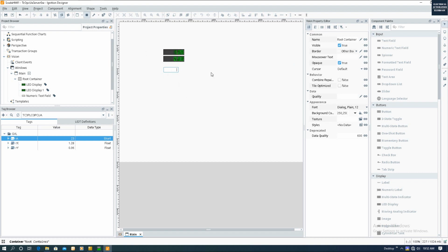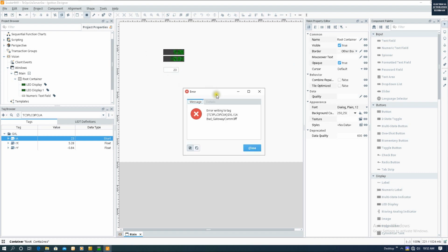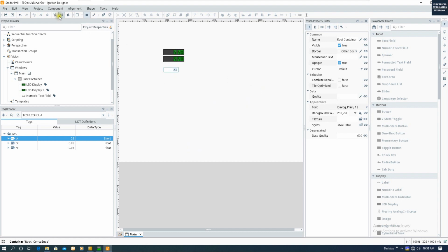So now I can type in a 45 value. Then we will find the system will pop up this message. It doesn't allow us to write the value in here. That's because there is a protection mode here. By default, that is the read-only mode. This is actually a very good feature. In case, for some reason, you accidentally type in a value, that value can directly write into the PLC, so maybe it will screw up something or accidentally fire up something.